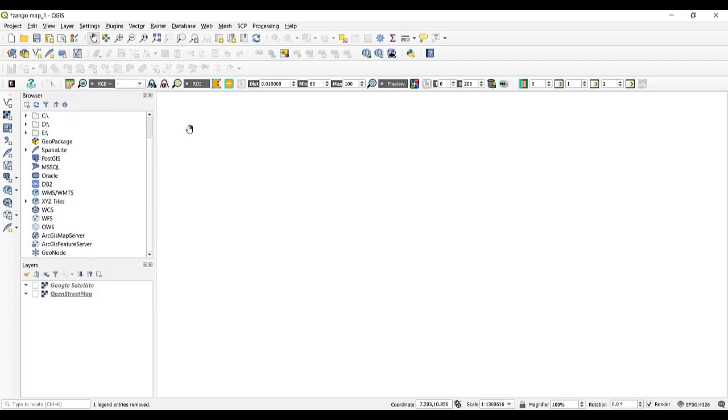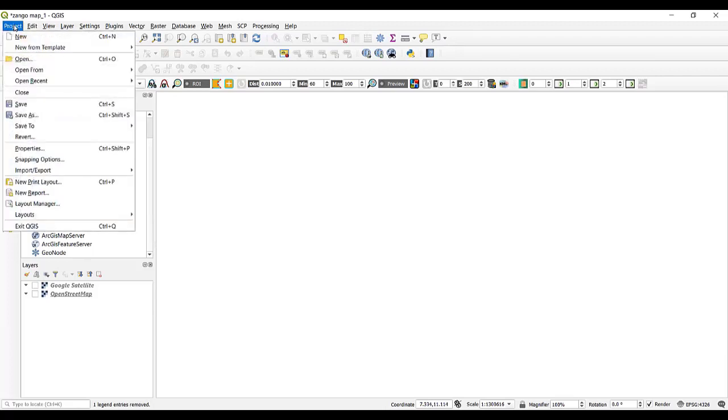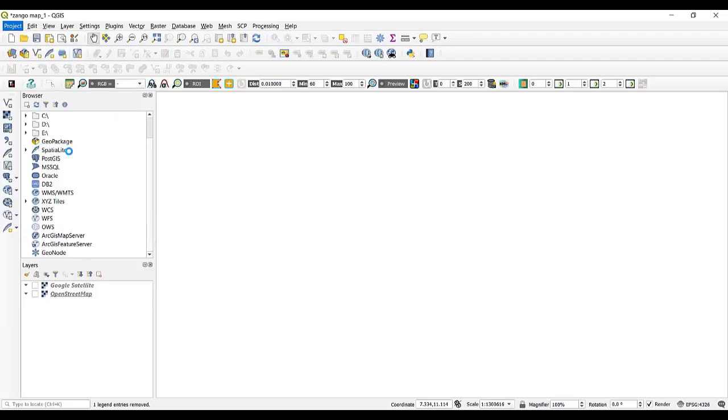Now, the first thing that you need to consider in GIS is the coordinate system, because we have different coordinate reference systems. There's something we call WGS and there's something called MINNA, or MINNA 32, 31. You understand? Depending on different zones. Okay. Now, the first thing you need to do is to select your coordinate reference system so that any point that you are loading will fall at the right position. Okay. So first of all, for you to select that, you go to your project, as you can see. Then you go to project properties.